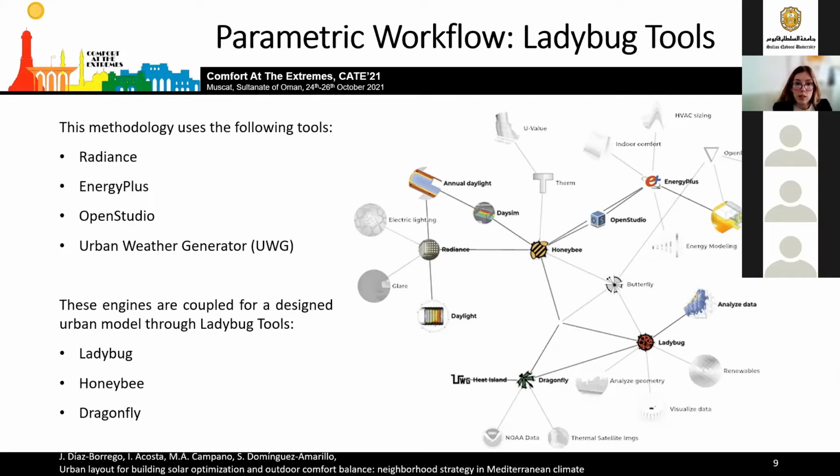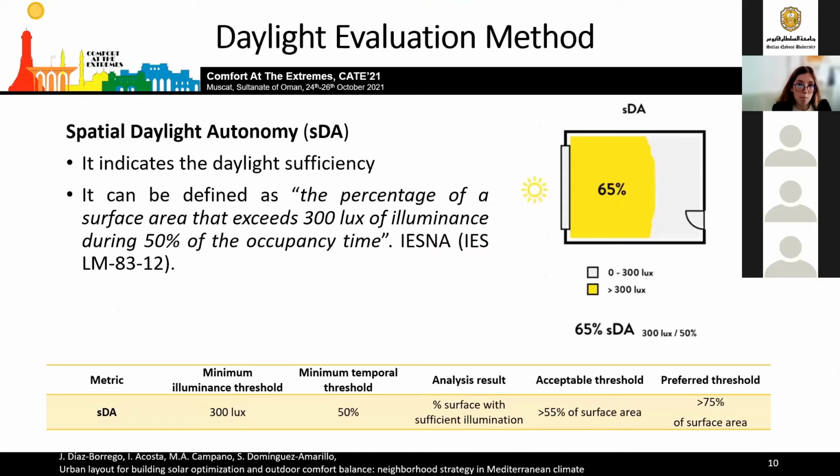And then the Dragonfly plugin allows UWG software coupling, which transforms the rural weather data, generating a modified weather file. And finally, Honeybee allows the evaluation of outdoor thermal radiation by connecting the Grasshopper workflow with OpenStudio and EnergyPlus. So Ladybug Tools make multi-criteria analysis possible.